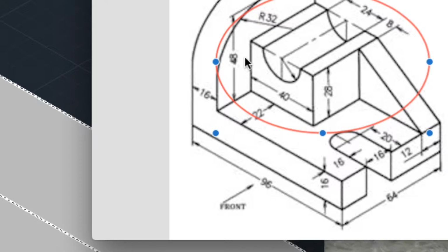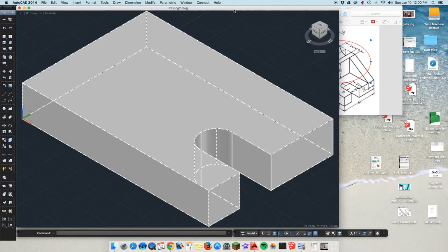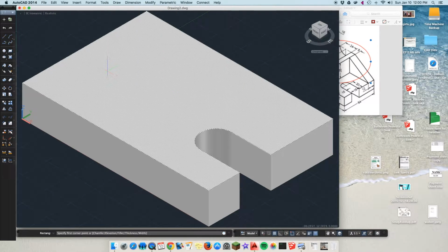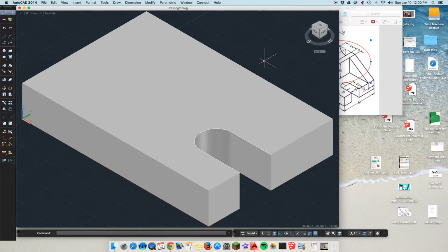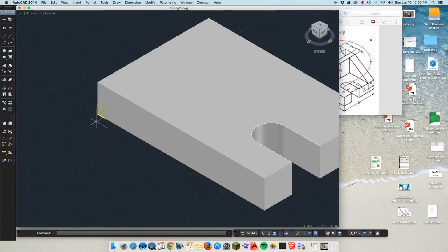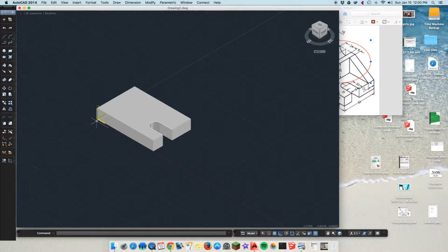So we're gonna make that, but here's the problem. If I try to draw a rectangle right now, you don't have to do this part, but you can just see what I'm trying to do. If I go back to my 2D drafting tools, click on rectangle tool, and if I start to draw, it's gonna be flat on the surface of this, okay? And that's not what I want. I need it up in this direction, okay? But look at where your grid is on your screen. The way your grid is laying on your screen underneath this object is the way that you can draw currently on the screen.